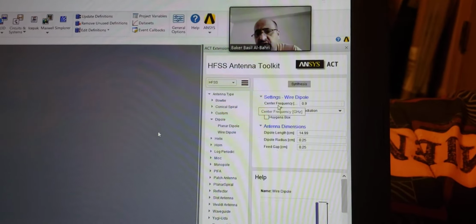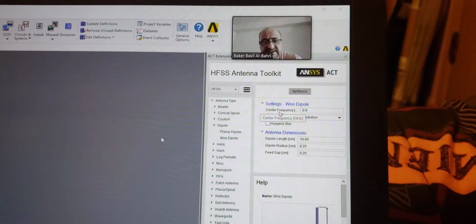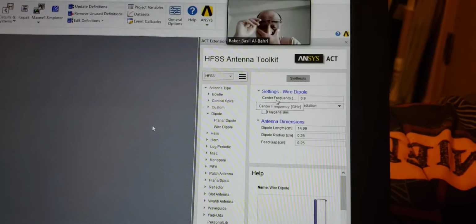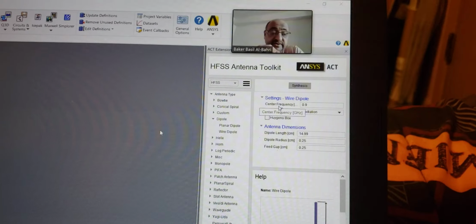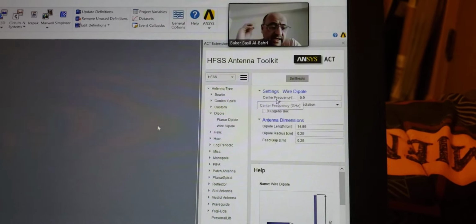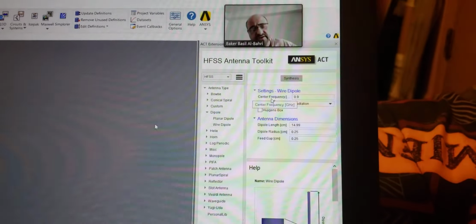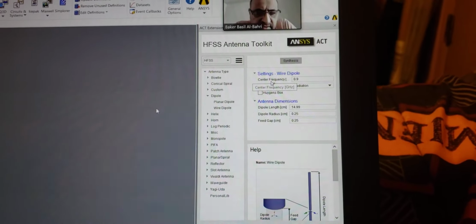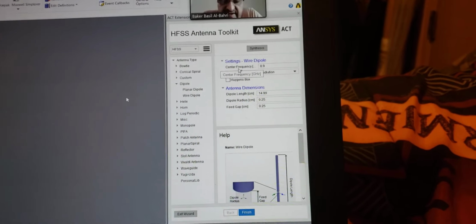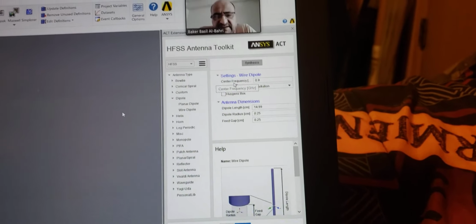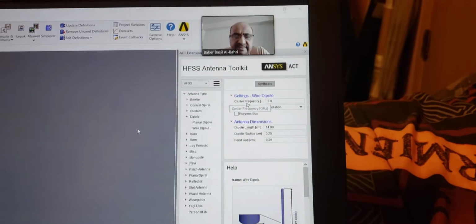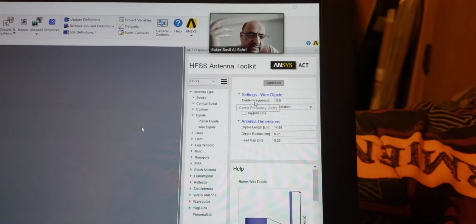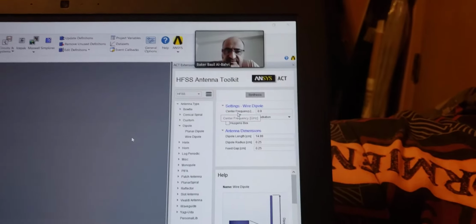So now, if you check the antenna in that router, you will find that the antenna is designed to operate at that frequency. If you take the antenna out and connect it to another circuit that generates different frequencies, say 1 gigahertz, it will not work. So there is a specific frequency that is used for each antenna. At that frequency, the antenna gives the highest efficiency, and we will see today some of these features.